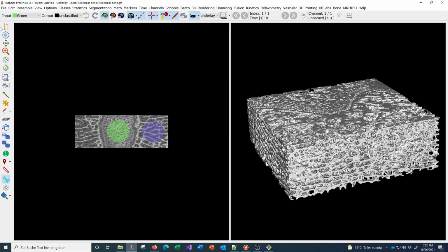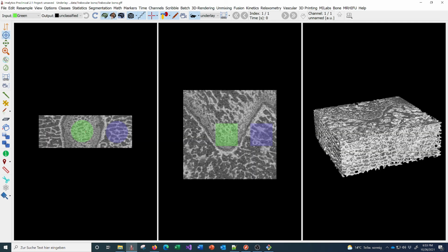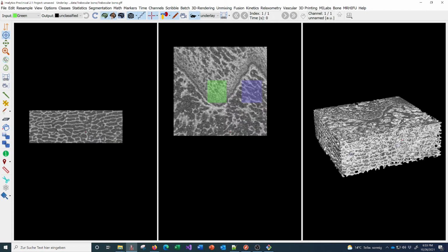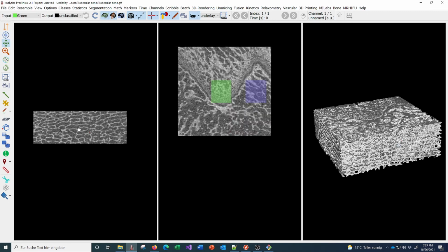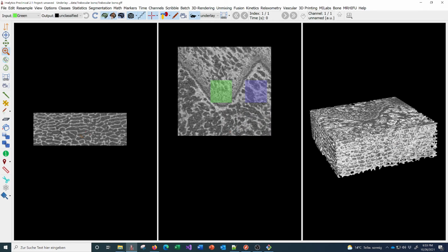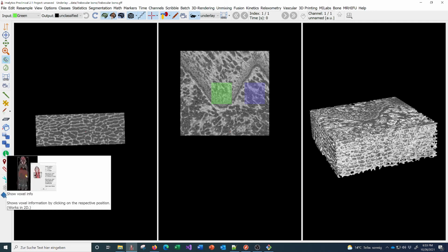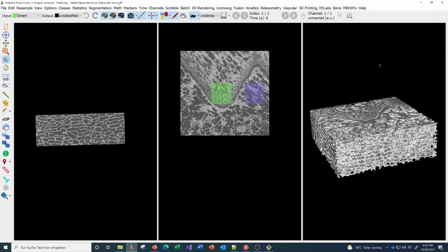And then here we have this vertical toolbar that is for the mouse modes, and those determine what you do. This is for slicing through. This is to jump somewhere, so if you click into this one, it'll focus all the views in there, and you can click somewhere in 3D and it'll jump there also. This is for panning, this is for zooming, this is for rotation. All these are setting what your mouse does. And that is also described in one of the next tutorial videos.